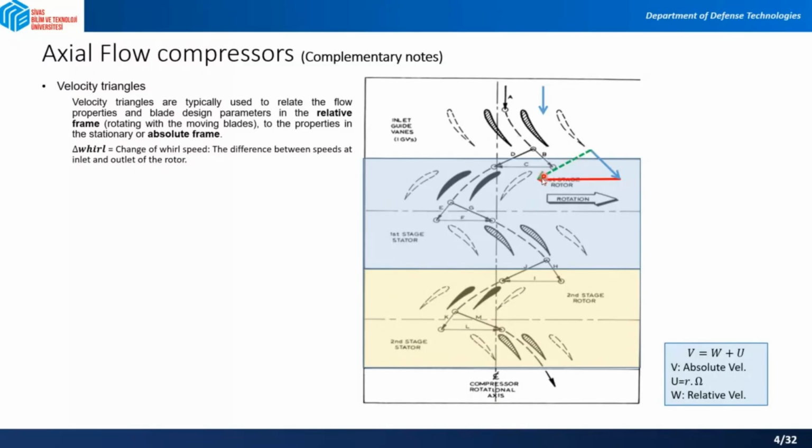So why are we saying that this is the relative velocity? Because this is a rotor and it is rotating. While it is rotating, we are facing the relative velocities, not the absolute velocity. And then you have to assume that this axial velocity that you had in here exactly preserves its magnitude in here. So the axial velocity in the preliminary design is not changing. Whatever comes in as an axial value, it is there after passing the IGV and at the inlet of the rotor. So this is the triangle at the inlet of the rotor.